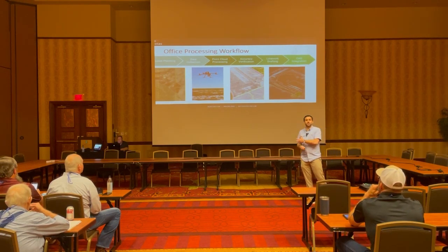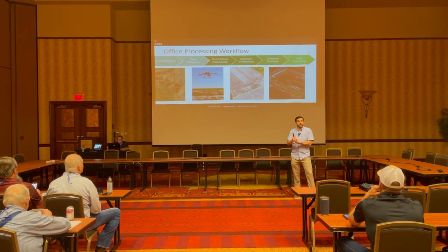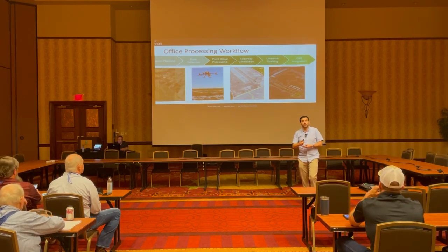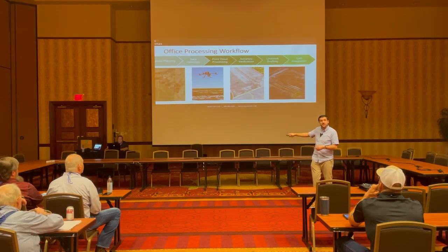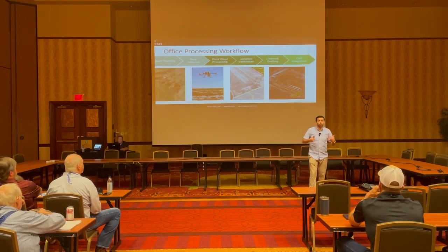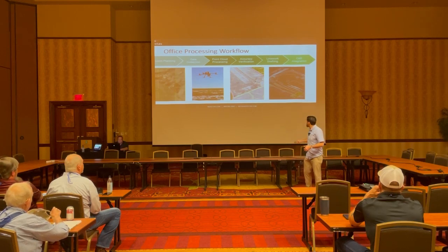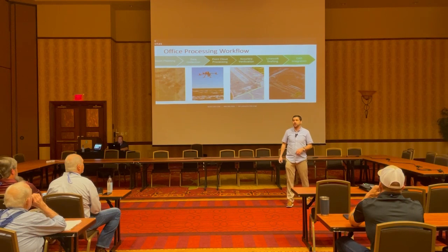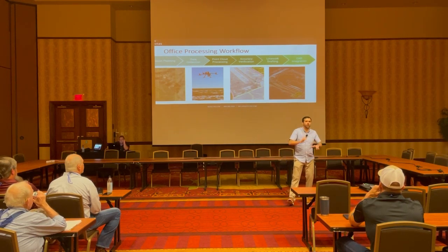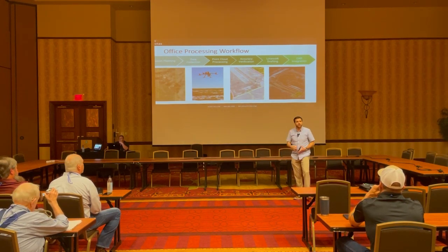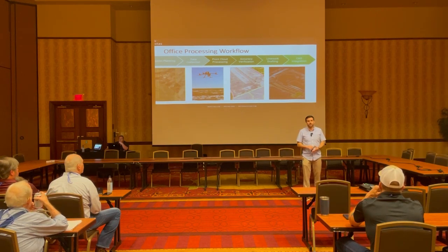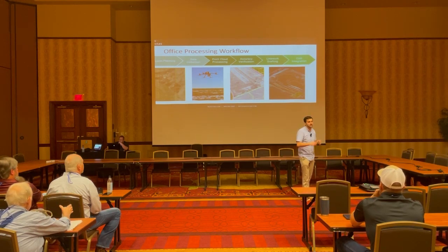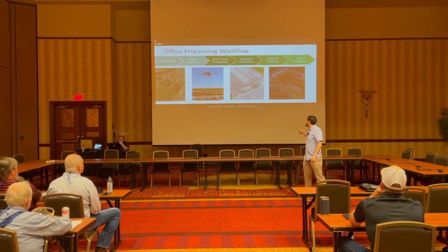So step one is going to be point cloud processing. That is, like I've mentioned before, the process of photogrammetry, which is stitching the images together into a point cloud or an orthophoto, as well as LiDAR processing as well. That's creating those full resolution, big file deliverables. Accuracy verification, taking those big files, making sure that they are exactly what you want. That's where all of that control that we were talking about and check shots came in. Making sure that if you draft survey deliverables on this, that it actually is accurate, that it lines up with your other projects, and that it is the quality that you want.